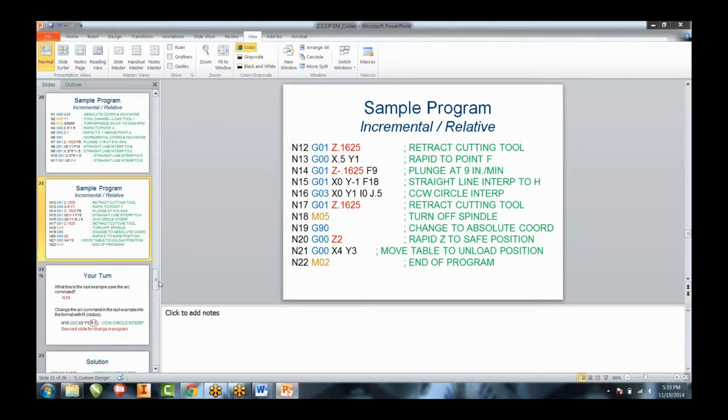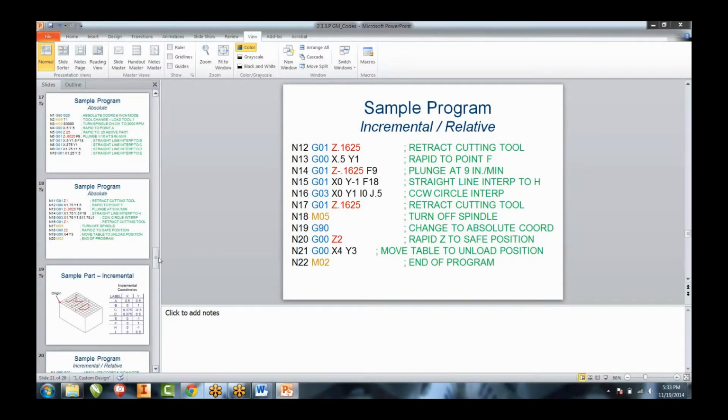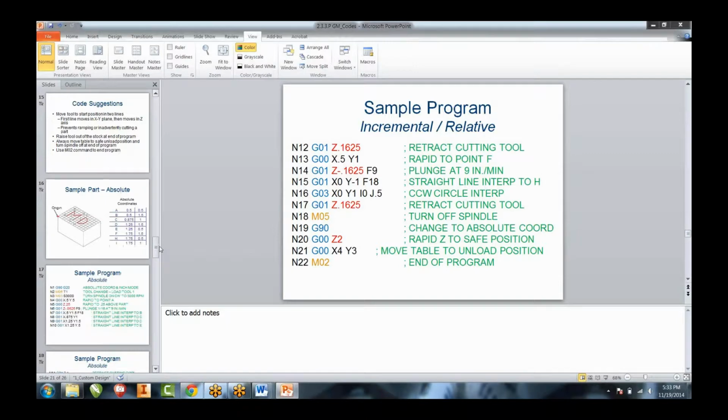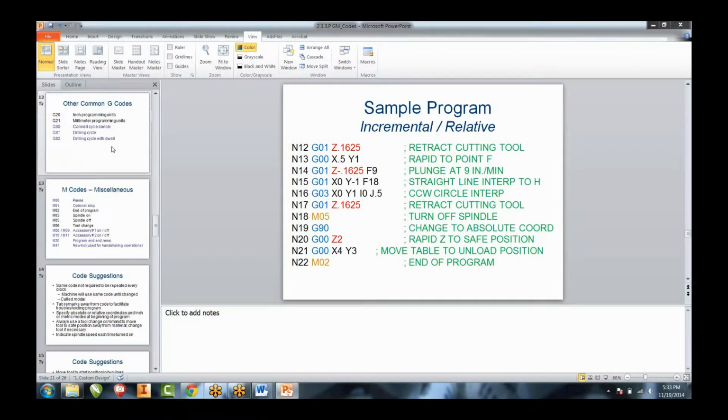So I told you a couple of little tricks that I teach the kids as far as memorizing. I go back up to it. And I don't teach any canned cycles. Things like G02 and G03, trying to help the kids remember which one is which. I try to make it easy, and this one is clockwise. That's 2 things, and this one is counterclockwise. That's 3 things. I don't know a much easier way to remember it than that. G02 is clockwise, and G03 is counterclockwise.